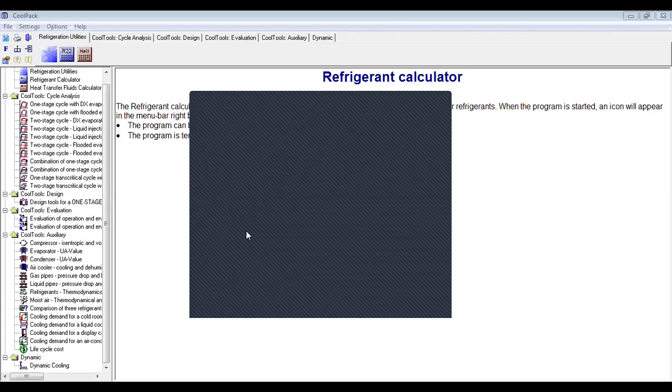Saturation, sorry. 100 degrees Celsius here. If this is for the saturation, we need to see the corresponding pressure. See, pressure within brackets. When you press this, you see 1 bar boiling temperature. If you need the specific volume, V of T, saturated liquid here.